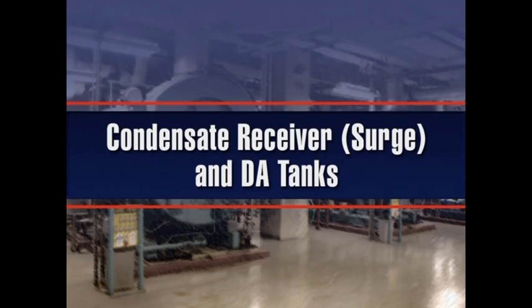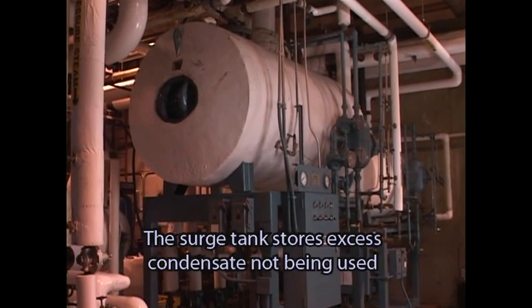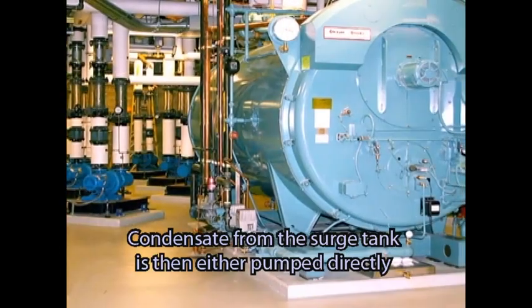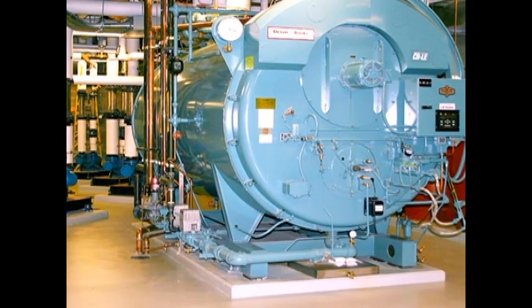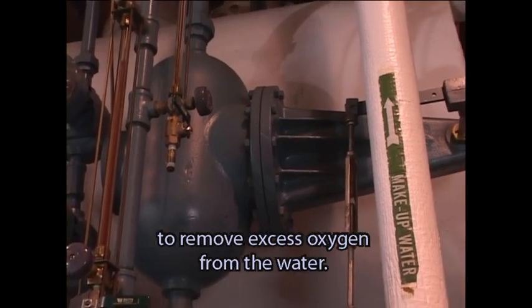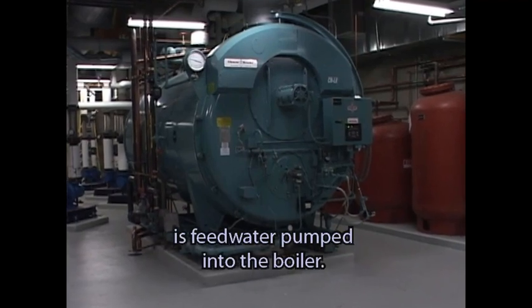Condensate receiver, surge, and DA tanks. In some plants, condensate is pumped to a condensate receiver tank or surge tank. The surge tank stores excess condensate not being used in the system. Condensate from the surge tank is then either pumped directly into the boiler or into a deaerator, or DA tank. The DA tank heats the city water makeup and returning condensate to remove excess oxygen from the water. The combination of city water makeup and condensate is feed water pumped into the boiler.